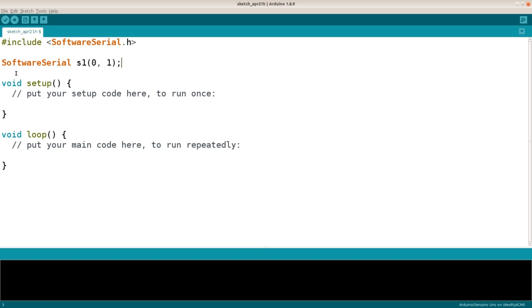So if you open the Arduino board and you check the pins numbering and naming, you find that the first two pins on the Arduino Uno labeled with 0 and 1 have the labels RX and TX. They are used for stream reading and writing and communication between the Arduino Uno board and the computing device and/or other devices that use serial communication. We are going to use these two ports specifically in a future section when we connect our Arduino Uno to the ESP8266 Wi-Fi serial module.